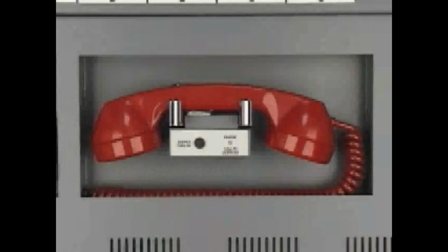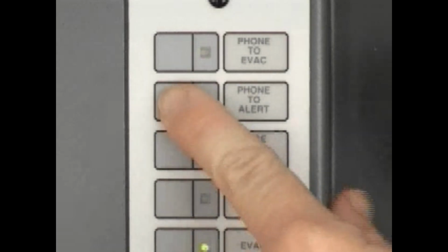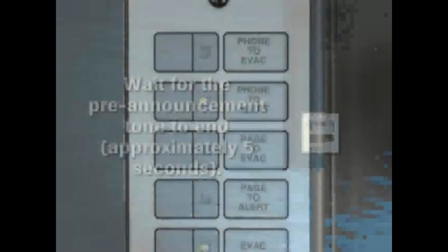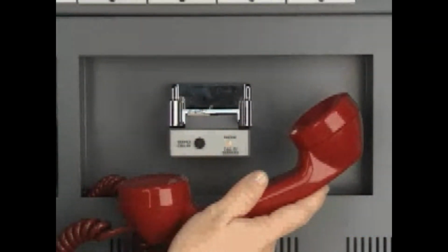To page using the firefighter's telephone, you need to establish communications with the telephone circuit, which is to make the page. Press the Phone to Evac switch to direct the telephone page to the evacuation area, or press the Phone to Alert switch to direct the telephone page to the alert area. Then you must wait for the pre-announcement tone to end, approximately 5 seconds. Once the tone is finished, you're ready to page by speaking into the telephone.